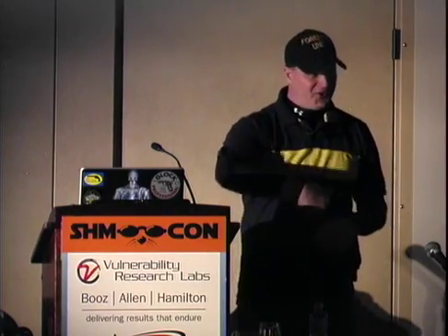And in some instances, like for instance, there are some laptop drives that are like 80 gigs, where the head is stuck to the platter. All you literally have to do is open the drive itself and turn it with a screwdriver without touching or scratching the platters. Turn the platter till it breaks the torque. It's called stiction, basically. We used to have this problem back in the early days when RLLs, MFMs, and stuff like that would actually stick.